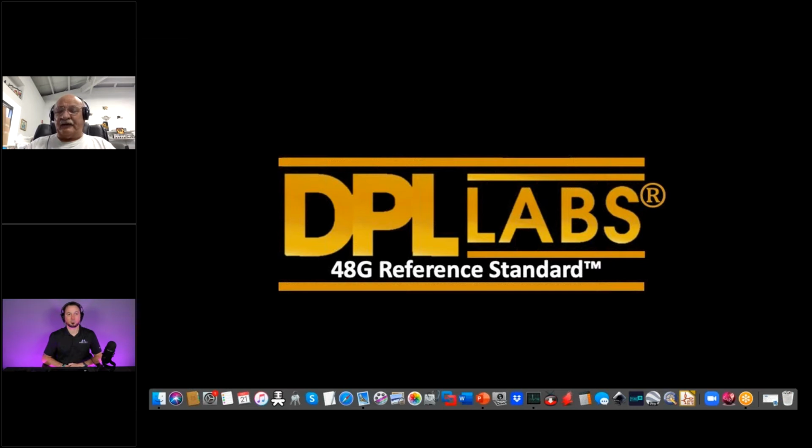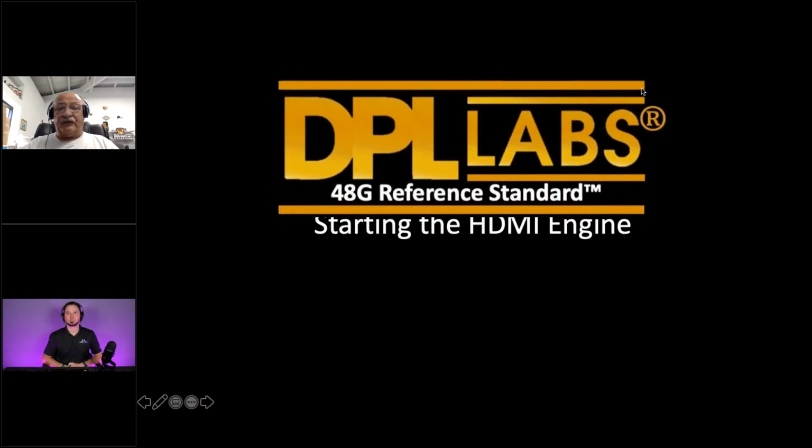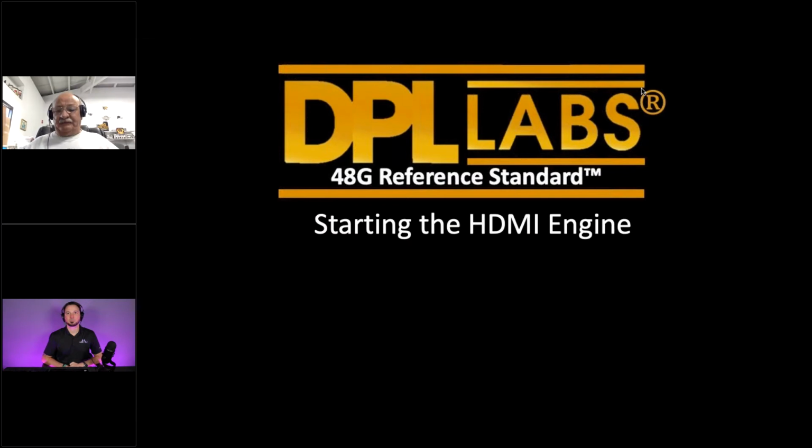So let's get started. The name of the session is Starting the HDMI Engine. And the first thing we're going to look at is what a signal configuration looks like in the HDMI interface. You've got this cable, and there's a lot in the cable. There's 19 pins, and out of the 19, only about 15 of them are being used. And there's a lot of common grounds in there too, so multiple pins are used for common grounds. So it shouldn't scare you that much.